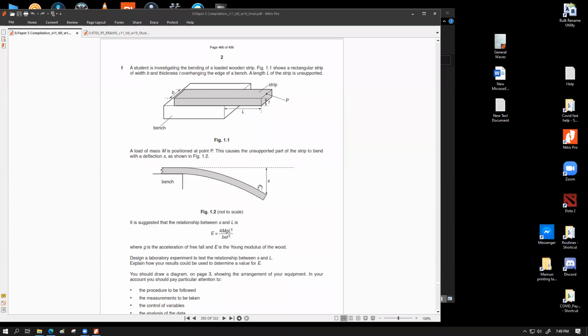So in my opinion, one achievable way can be that we have a string or metallic wire pinned with a nut screw somewhere over here, that should roll over this strip and come over this point and make a hanging pot, or a hanging mass system, and we should be loading those masses onto this part. That way the top surface will be perfectly free of the loads. Your load would be located somewhere below, but you would be applying the loads exactly on this exact point on the upper edge of the wooden plank.